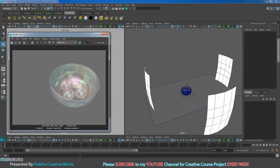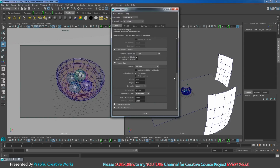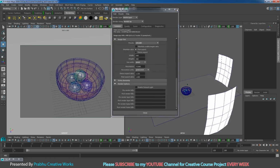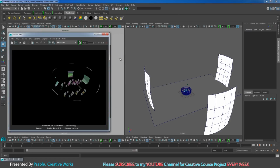See here, we have no light in our scene, but you still see lighting in your scene. Go to render settings, in the common tab go below. Here we have render options. Turn off enable default light. So I will select my viewport and click render. Now we don't have any lighting in our scene.